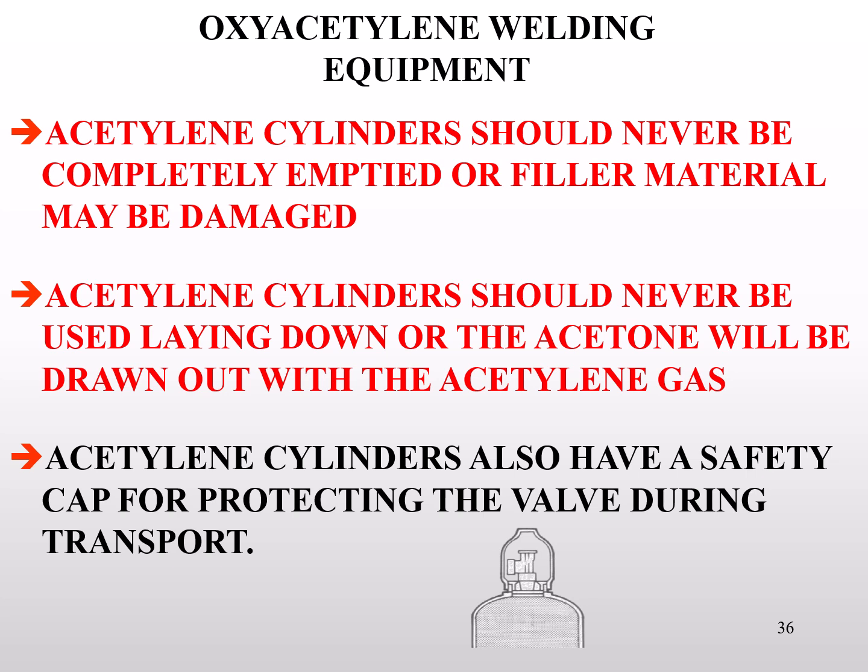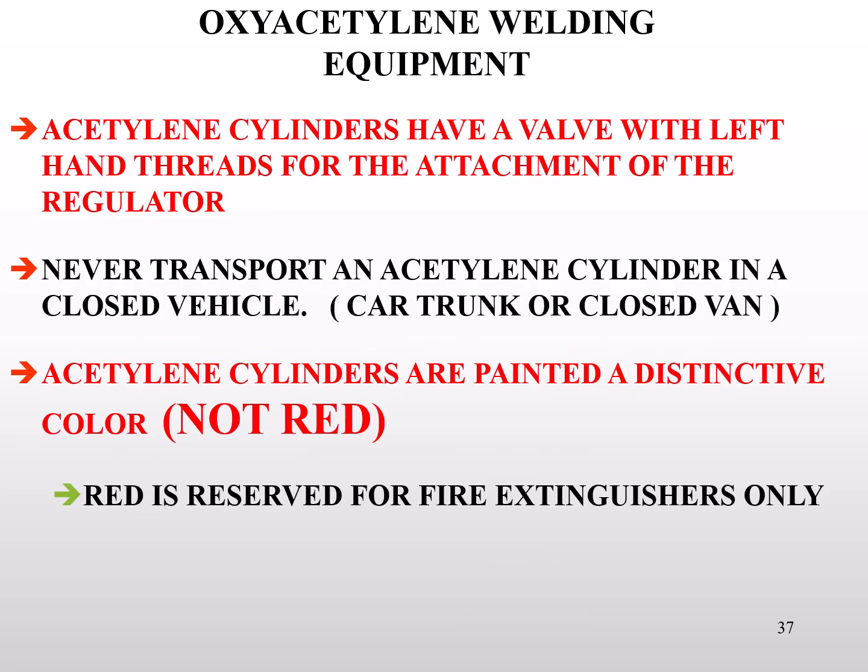In the end, you will use up acetylene very quickly, and the cost to replace it is fairly expensive. So all acetylene bottles should only be used while standing up. Many times bottles have been laid down in equipment in order to transport. That is fine. Just make sure you stand it up before you start using it. All acetylene fittings, hoses, and equipment have left-handed threads. That's a key point. Therefore, oxygen and acetylene equipment could never be hooked up in reverse, which could create a very dangerous circumstance.